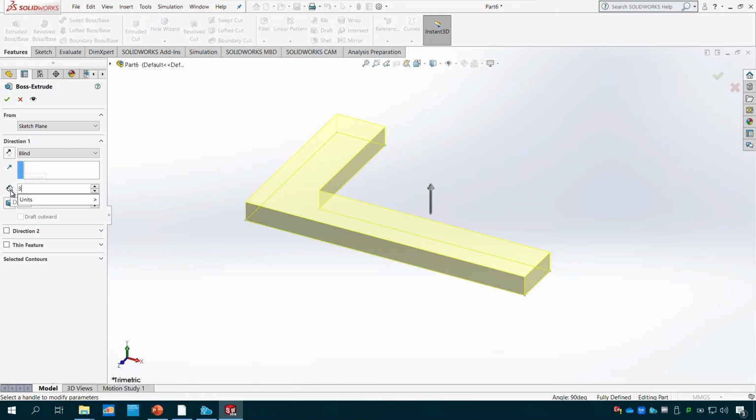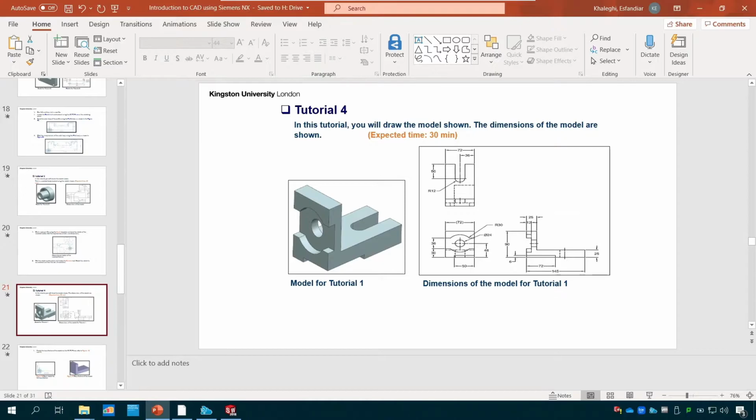So let me open up the file. We made that one, and now what I'm gonna do, I'm gonna make these parts. So I need to make a rectangle 72 by 6, as you can see here. Something really important is basically to find what plane you want to use. I need to pick up that face as my reference plane. Because otherwise what I then draw doesn't actually help me to do that cut. So it's really important that's the plane I'm gonna pick up.